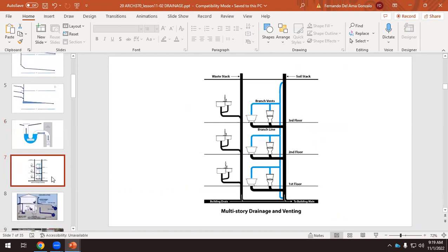Okay, so here, this is interesting, and this is something that is half good, but it's not well solved. Nowadays, I think in most of the towns or most of the cities, we have to separate the black water and the gray water. So what is black water? Everything that comes from the toilet is black water. And sometimes they consider the water that comes from the shower or bathtub as black water, because it's in touch with the human fluids.